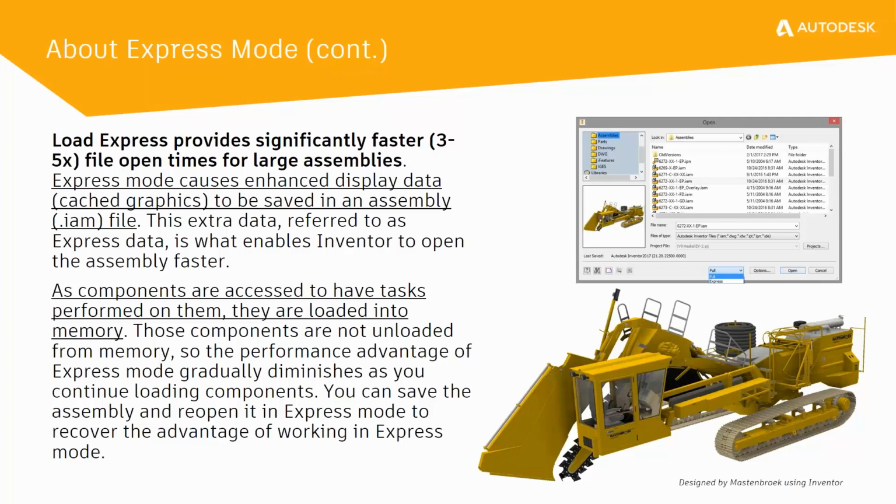The good thing is that as components are accessed or you need to perform tasks on them, they're then fully loaded into memory. What you'll realize in using this workflow is over time, as you load components, you're working with sub-assemblies and components inside of sub-assemblies, that gradually the performance may degrade because you're essentially converting an express sub-assembly or component into a fully loaded one. But the good thing is that you can simply save the assembly and then reopen it, which will then reopen everything in Express Mode again.